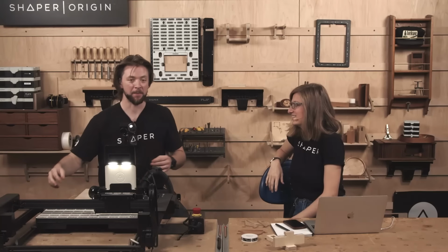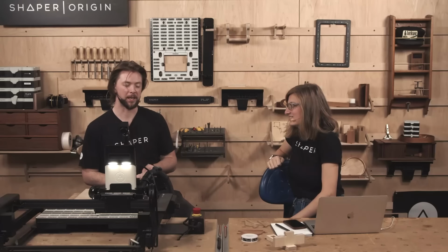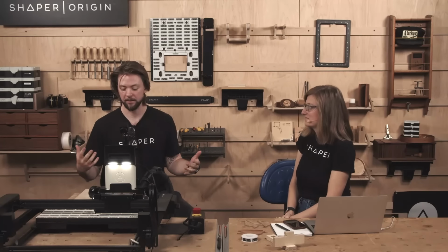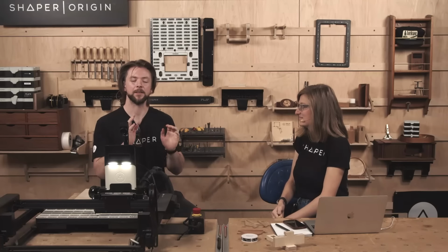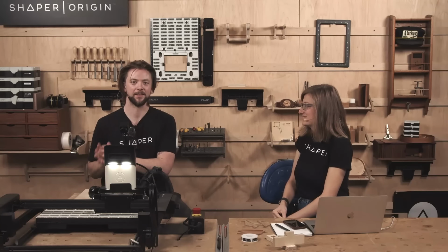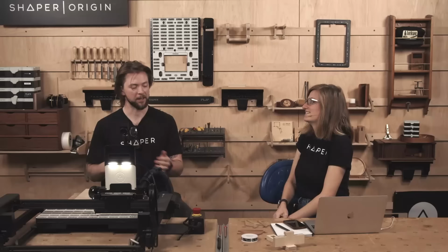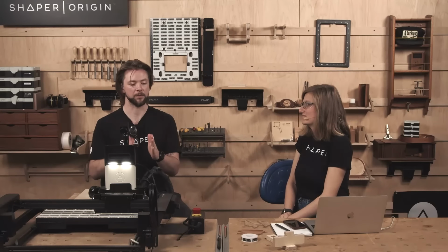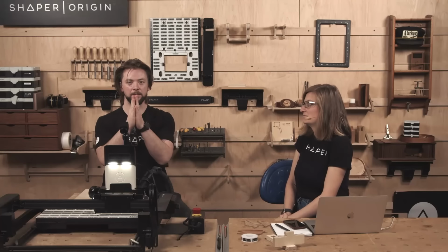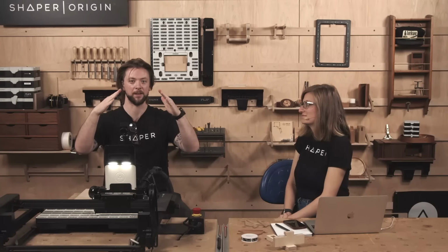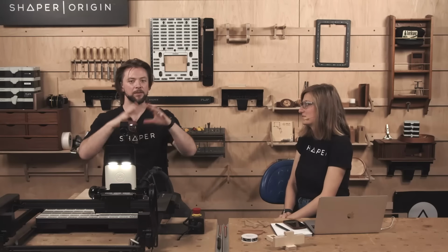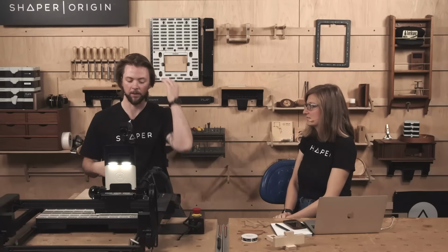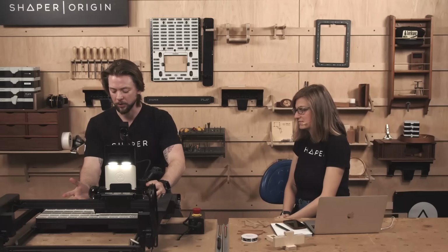In the interest of time, I'm just going to go straight to what I am pretty confident is going to fit. It's another -2 offset on the pocket. So that's -2 on all the positives. I'm sorry, -0.002 offset. 0.002 of an inch. If you think about it, if each part has that little tiny bit off of it, it kind of compounds. So 2 thou, 2 thou, 4 thou, 2 thou, 2 thou, 8 thou. Right. Yeah. So it works out to be a total of 0.008 of an inch tolerance around the whole thing, which is great.